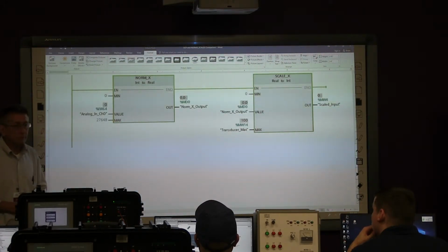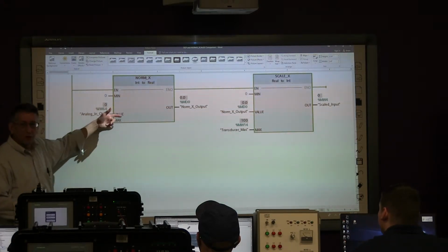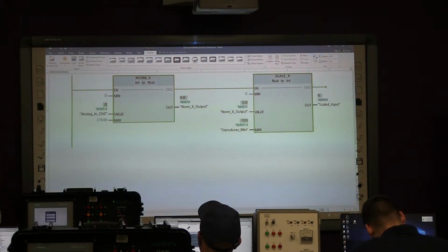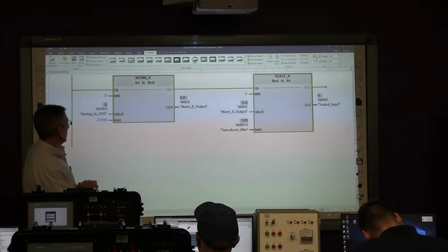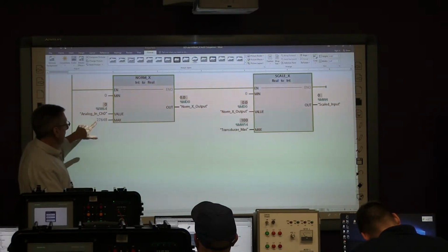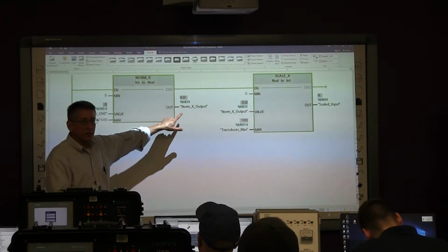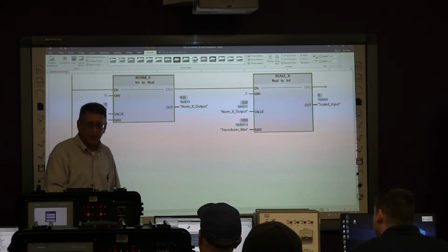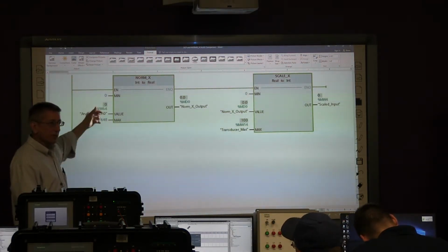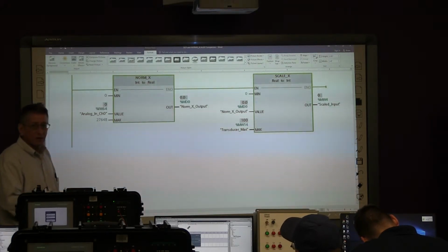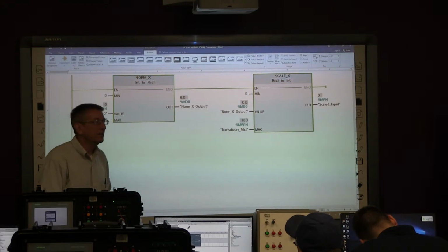And what about input? The input value is actually right off the transducer. So at maximum input, what's the value going to be? 1.0. At 50%, at 5 volts, let's say, it's going to be 0.5. So you get it.